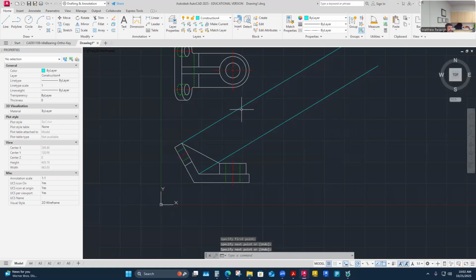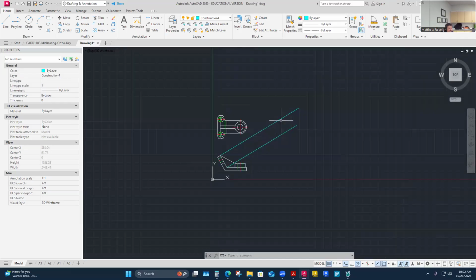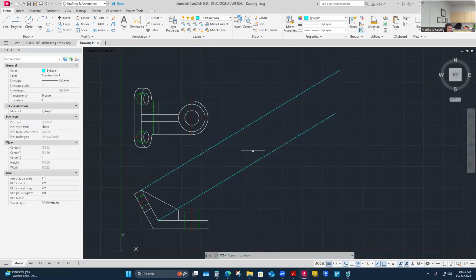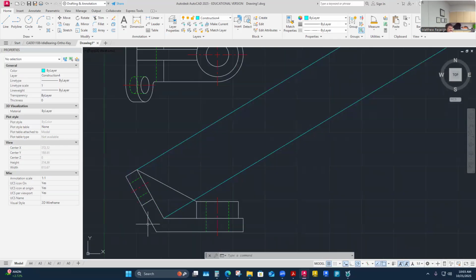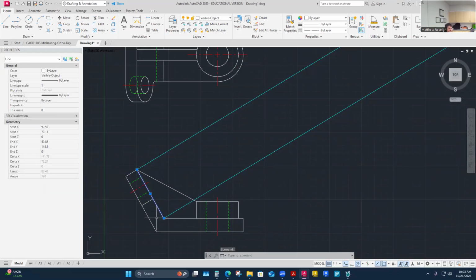Knowing that I will be dimensioning here, if I place this here, I'm going to be dimensioning in here. So this thing's going to have to come out and probably catch its own viewport. So I just might get it away a ways here. If I put it out here enough, I might be able to get everything in one viewport. I don't know. I'm not going to be too crazy about it, but I'm going to do this partial auxiliary view. I think I'm going to offset this piece across my plane there.